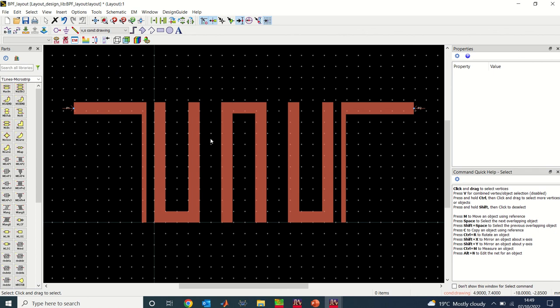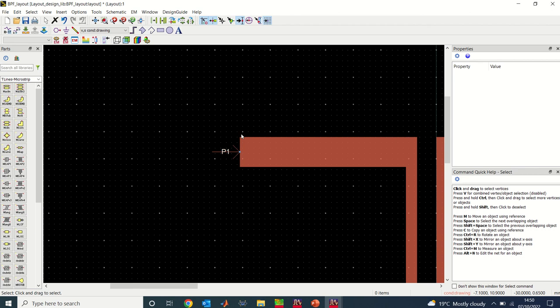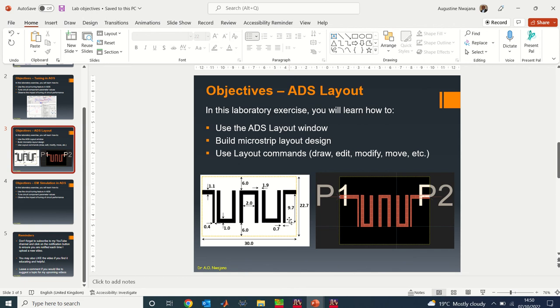For us to put that box, the easiest thing I can do is use the construction line as a guide. I can put it without that, but let's just go. I want to put a construction line at the point where I want the box to be implemented. Now, if I go back to the design, you can see that I want this to be 6 millimeters from the design and 6 millimeters from the design, and of course to touch the input and the output.